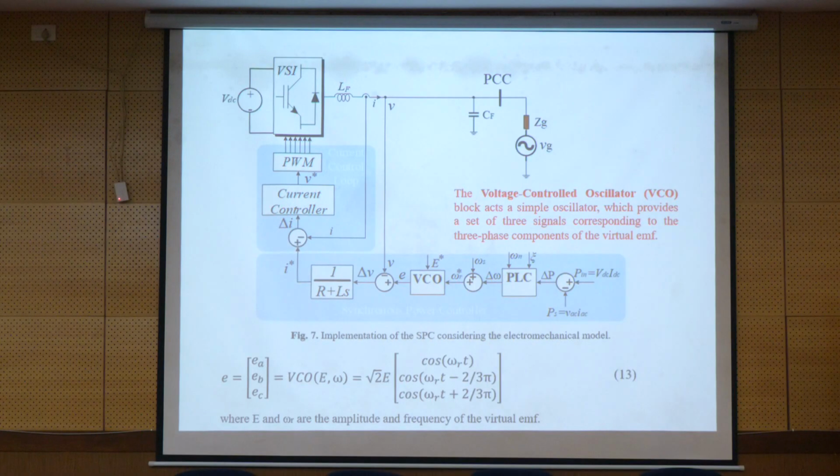So W is 1 over 2 J omega squared. Omega is the constant, J is the inertia. So we have the kinetic energy, and J can be calculated from here, or we can say that this is how much energy we need to inject into the grid as kinetic energy.